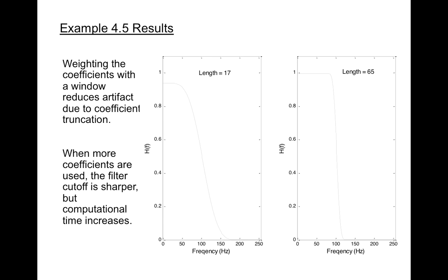The disadvantage of going with the longer filter is that it does increase your computational time because you are increasing the filter order.